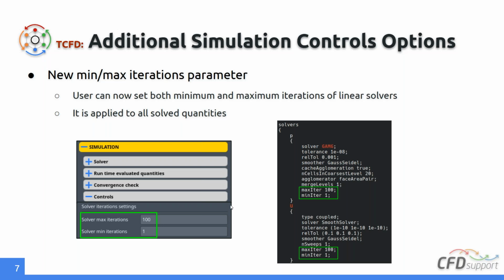So this is useful, for example, when we are playing a lot with respect to the acoustics. We are playing a lot with the transient solvers with really small time stepping because of resolving all the frequencies. And the thing is about the tolerances. If you have really small time stepping, then the tolerances sometimes have to be decreased. Otherwise, for some quantities like turbulent or temperature quantities, the absolute tolerance is satisfied because of small time stepping. So then the solver does, for example, zero iterations, and the solution doesn't change anymore.